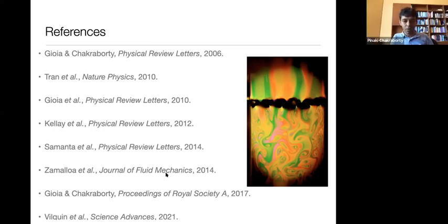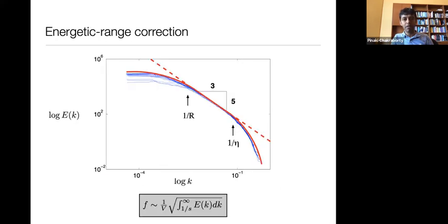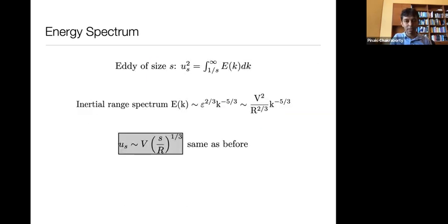Sure. So let's go back to part over here. The Reynolds number dependence comes in two ways. We have the very base model, which is the Kolmogorov model of the energy spectrum, epsilon^(2/3) k^(-5/3). And there's a constant in front, the Kolmogorov constant, but for everything we are doing, that's just a scaling factor. So it has no effect on any of the results that we're describing so far.